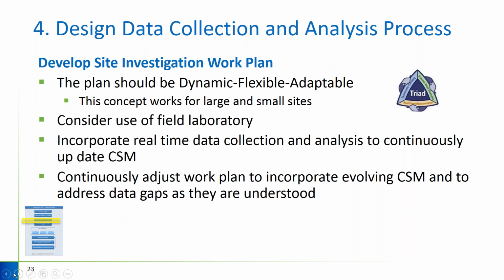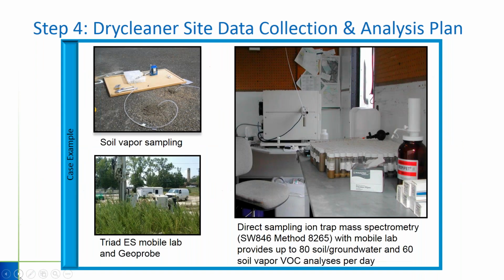However, if there's some subsurface condition that you find when you get into the field, where maybe 15 out of your 20 planned collection points you can't do because there's some obstruction or some utility, then that's probably something where you should convene the project team and decide what you need to do. You can define that decision-making process in your work plan: how much can the field team leader or the lead geologist, or whoever is leading the program, change on their own? And at what point do we have to stop work, re-engage everyone, and decide what to do?